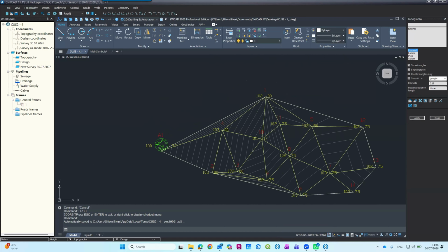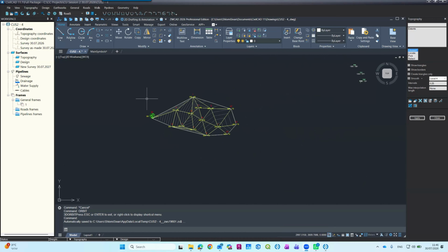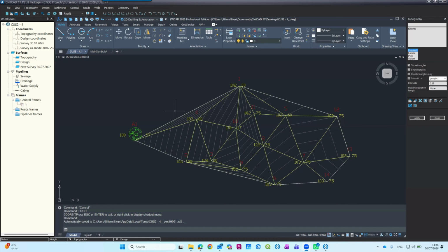Is the triangulation of a point done between the closest points until all the points are done? Okay, first of all, good questions. I will start one by one. Let's start with the last one. The question was how the software knows how to stop the triangulation. The software goes to what we call a convex hull. This is the convex shape of the surface.